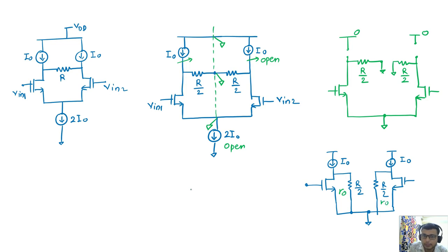So what I can say here, if now we switch to the practical circuit, switch to the lambda not equal to 0 case, it means R out is not equal to infinite. Okay, so this thing can be concluded from here. Any particular R connected between two differential structures behaves like nothing but their R naught when we virtually short it.